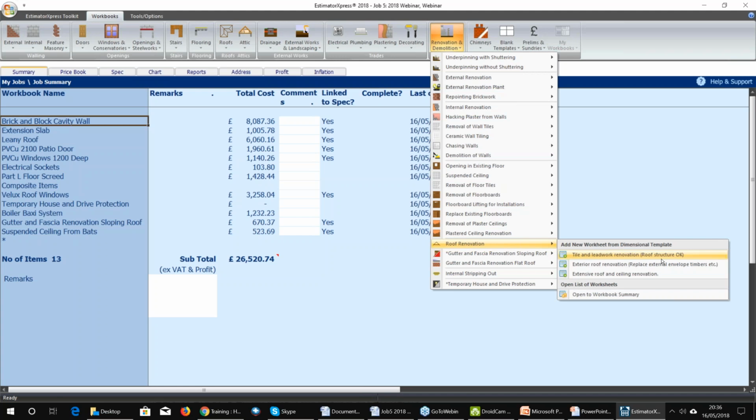But if it's not something you've normally tackled before, then yes, there are certain things to look out for and account for. When you're stripping off roofs, it's one of those times like a lot of renovation works where it's like, oh, look what I found, this rafter's rotten. Or in my case, from some of the work I've done in the past, oh look, this rafter's half burnt through. Incendiary bombs from World War II, and just felt battened over. So yeah, it wants an eyeball on that one.